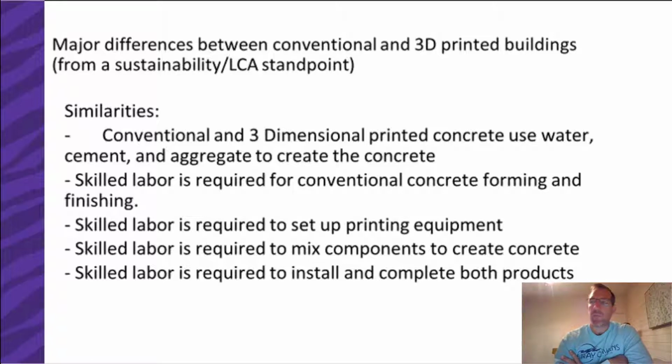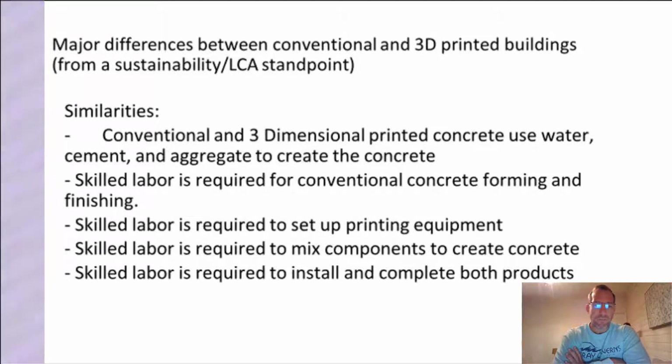Also, skilled labor is going to be required to do any testing or inspection process before, during, and after you pour your concrete. You want to ensure that you do your break test at 7 days or 30 days, whatever your specifications require, and ensure that the concrete has met the strength specifications of the project that you're working on. So these are some areas where skilled labor is still going to be required on both applications.